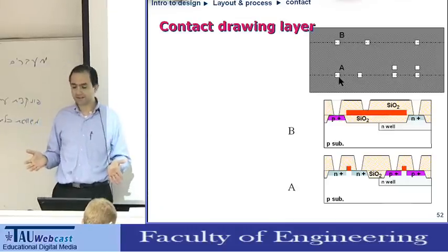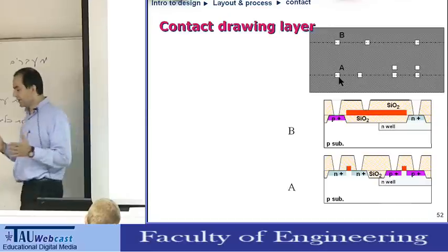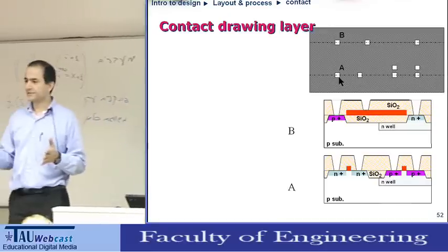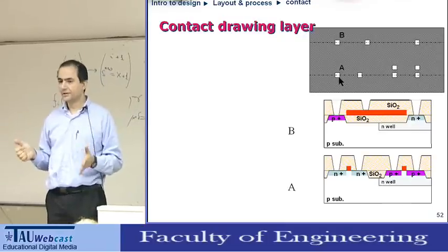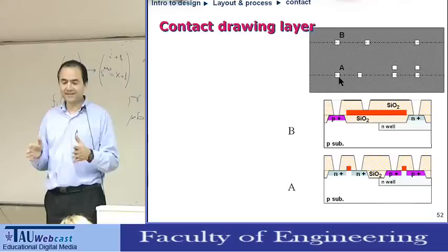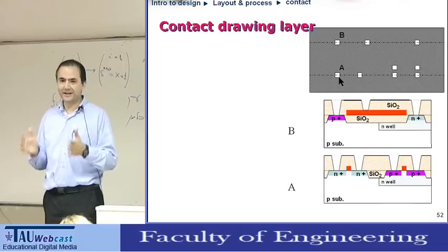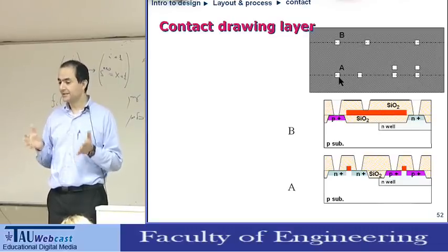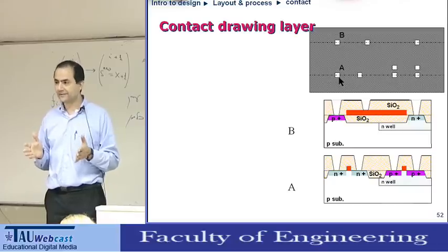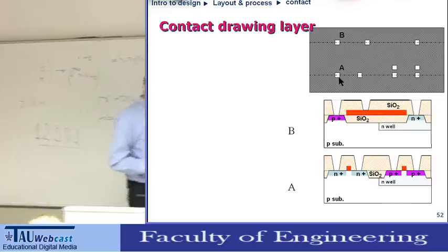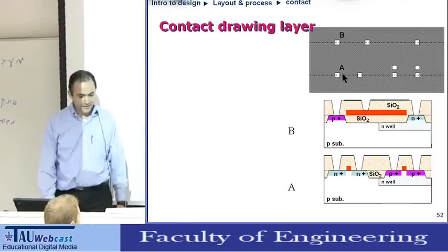I can tell you that in a process which is 3 generations old, today we put all the transistors, sometimes even more than one, in the area that previously we put 1 contact. And the contacts today are more resistive, but they're much smaller. So we will try to save space, and we'll use the best lithography we have.